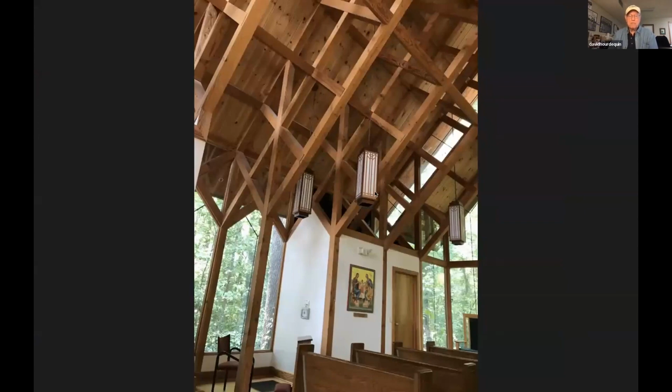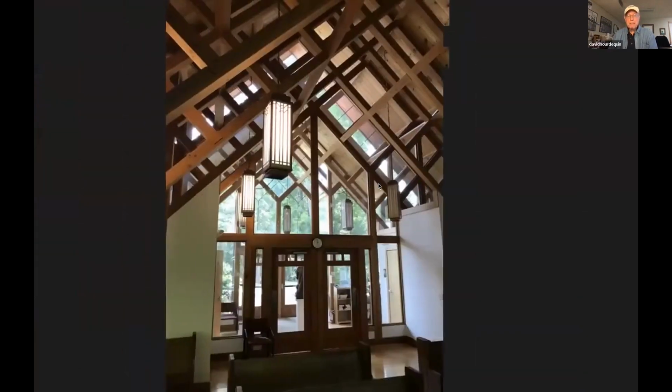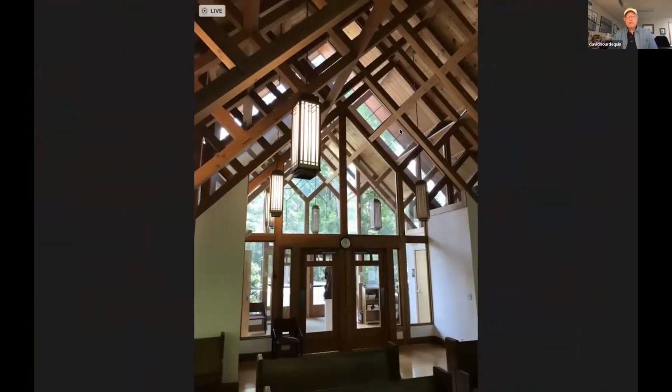In other words, if there was a continuous piece, let me see if I can find another slide. Yep, sorry about that. Don't mean to make you dizzy. If there was a continuous piece in here, like right here, that was fine, but we needed to find a way to connect these two pieces that were interrupted by the bottom cord of the truss. And same thing within the truss cords. Everywhere there was a discontinuous piece, there was a timber link across that.